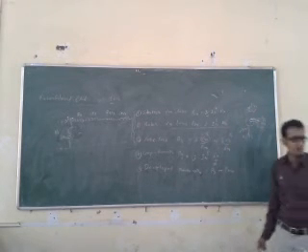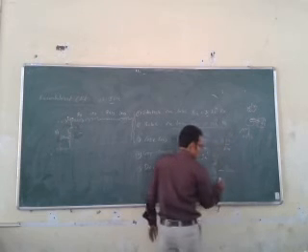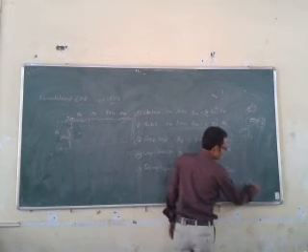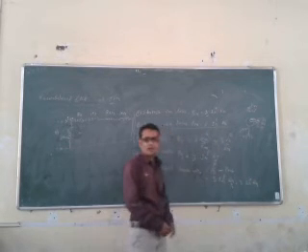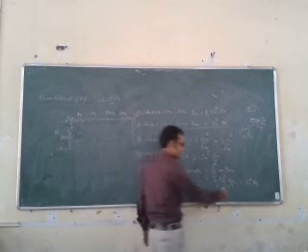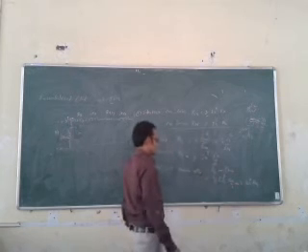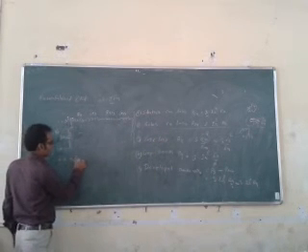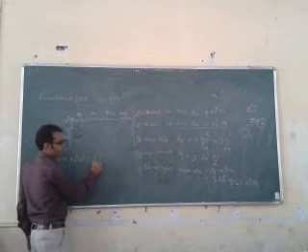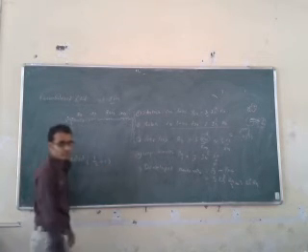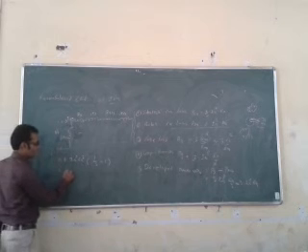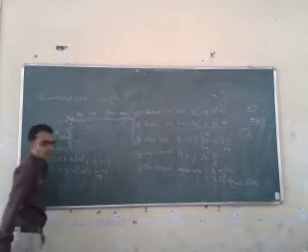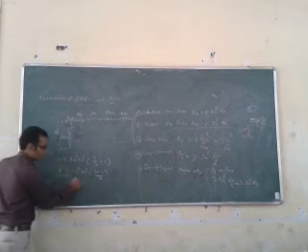PG minus PR is equal to 3 times IR square RR by S minus 3 times IR square RR, which is equal to 3 times IR square RR into bracket 1 upon S minus 1, which is equal to 3 times IR square RR into (1 minus S) upon S. Now what is the value of this?